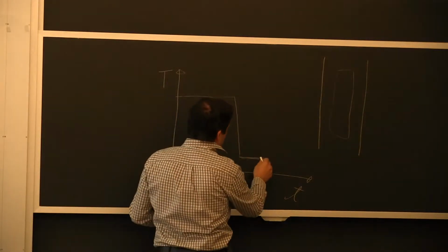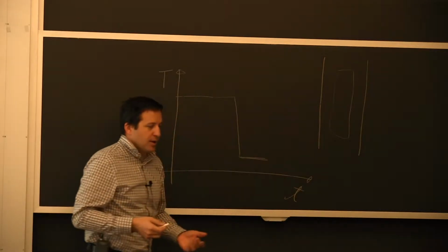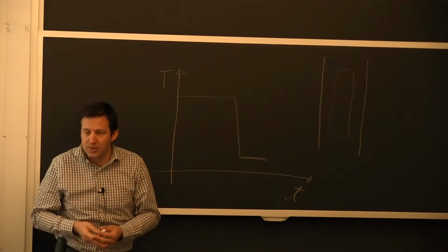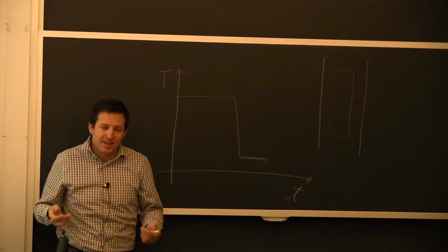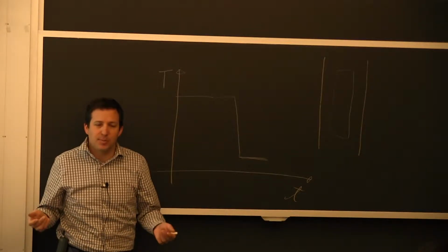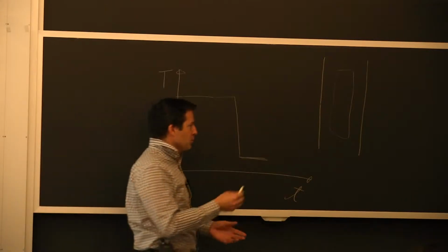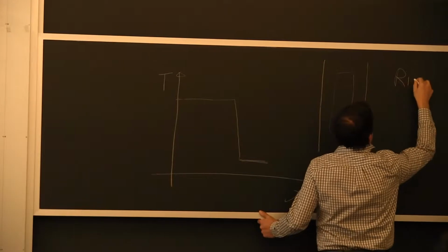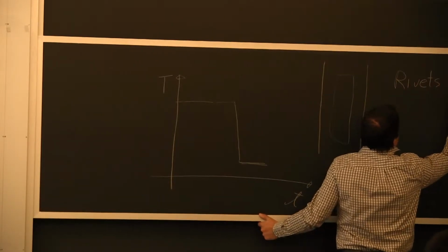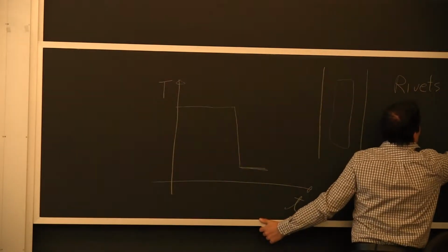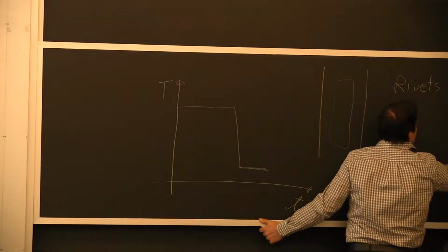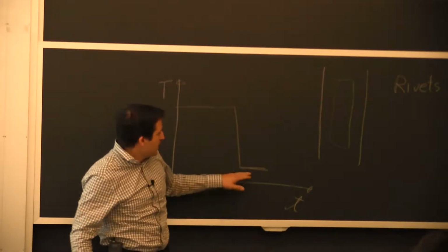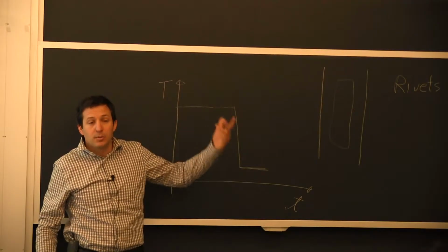So what you do, depending on the alloy, I mentioned briefly about rivets, if you remember, rivets for aerospace. What I was saying, it's essentially a 2000 series aluminum alloy. If you remember from yesterday, the tempers, there's a 2000 series with a T3 temper, that's ambient temperature. It means that you don't have to heat it up after, but you are forming precipitates.